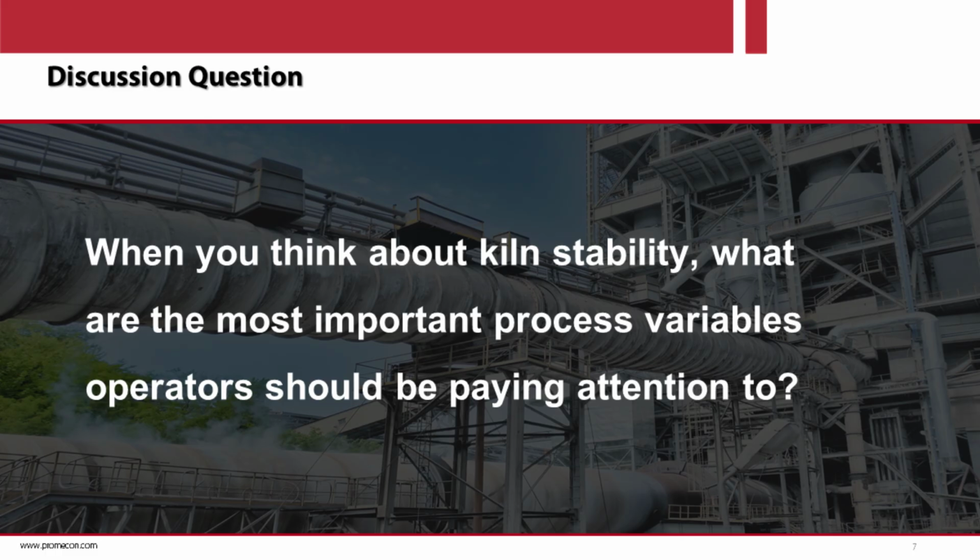For instance, you could see that you're lacking oxygen at the preheater because you're focusing too much on the kiln. And of course, you have also the feed rate versus the fuel rate. And of course, we should not forget the kiln shell temperature that you follow with the scanner, for instance, which is a good indicator of the coating issue, build-ups inside of the kiln, and potential refractory loss inside of it.